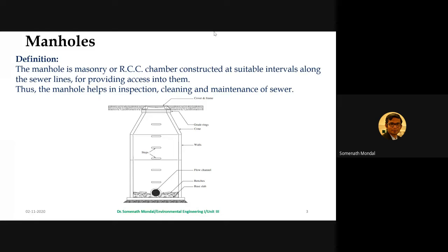Now, apart from whatever I have discussed, manholes have another very important role in the proper maintenance of the sewer pipes. Sometimes toxic gases, which are very pungent in nature, are produced within the sewer pipes. Most of the time, you will see that these manhole covers have some slits or voids in them, so as to have proper ventilation of the manholes.